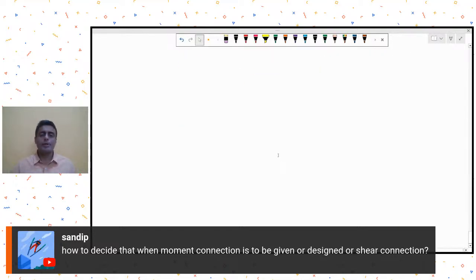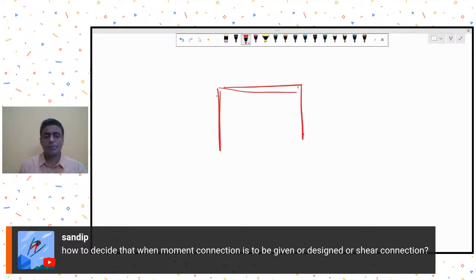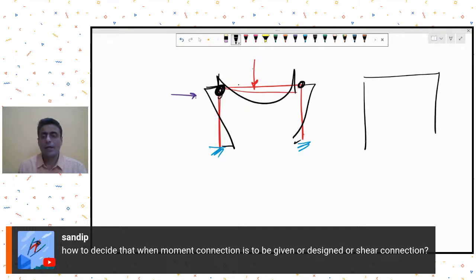and that will depend on the choice of the structural system that you adopt. The basic concept is this: if it was a case of simple gravity load, first of all you also need to ensure lateral stability, stability in the vertical direction. But suppose I were thinking of a system which is to take lateral loads plus gravity loads both. Now in this system, it's a rigid portal. That means these connections are rigid. What will happen? This system can remain stable because it can develop moments for gravity loads also, and it can effectively counteract the lateral loads by developing end moments over here also.